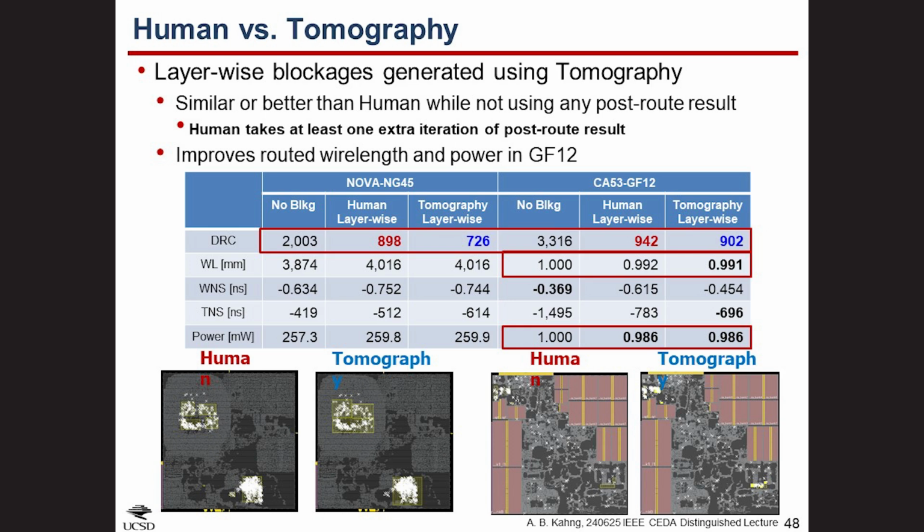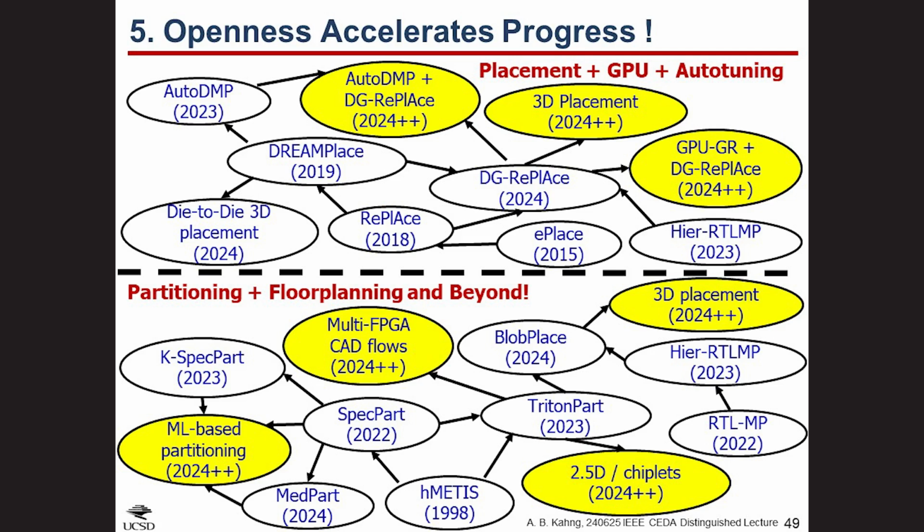This slide shows a commercial synthesis tool's noise or chaos for the AES design in GF12 with a triple VT cell library. So the baseline target period in this picture is 280 picoseconds, and we step it by 0.01 picoseconds. That's 1/100th of a picosecond for 100 steps to the left and 100 steps to the right. So in these plots, you are seeing the results of 201 synthesis runs that vary only in the clock period constraints. And all of these runs sit within a 2 picosecond interval.